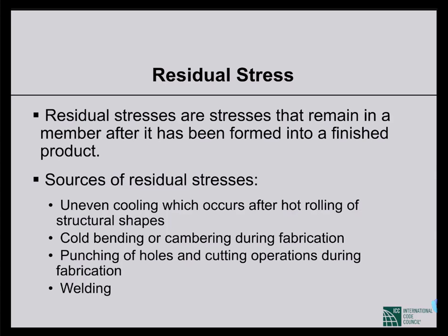Residual stresses are stresses that remain in a member after it has been deformed into a finished product. In case of steel, we define residual stresses like this: after production of the section, the stresses that are inbuilt within the member, just after production. The members may be a finished product from a factory.